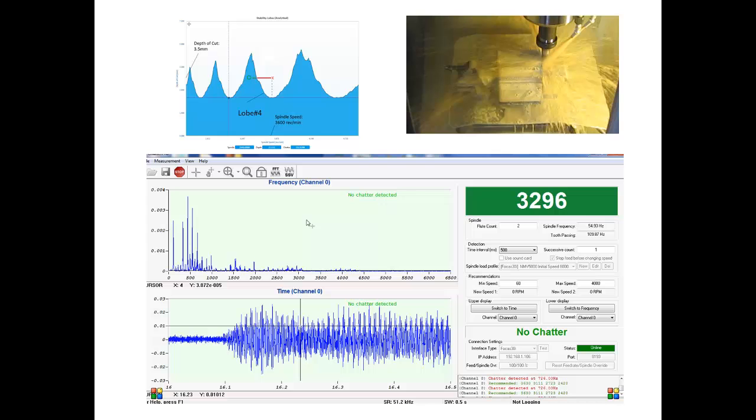In this cutting test, the machine is operating at 3,600 revolution per minute, with a 3 mm depth of cut. The material being cut here is free machining steel. ChatterPro automatically detects the presence of chatter by listening to the sound, then automatically changes the speed to put the machine into the blue stable zone. And the video shows how the machine is controlled automatically by ChatterPro, which kills the chatter and stabilizes the spindle at 3,462 revolution per minute, where chatter disappears.